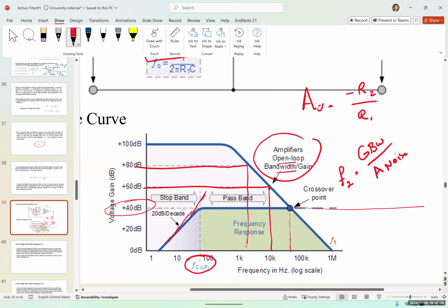So at this point, actually, it's gonna just directly come back. So you're not gonna have a very good frequency response. If you have 80 dB gain, for example, your frequency response would look like this, which would be a very, very limited frequency response. So the lower the gain is, you're gonna have a wider frequency response. The higher the gain, you're gonna have a narrower frequency response.